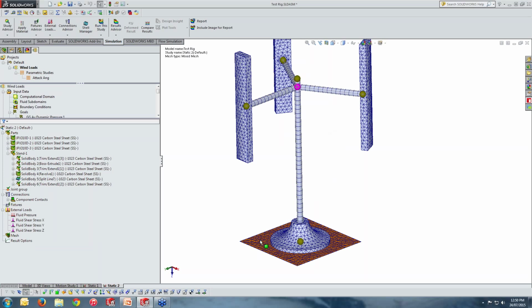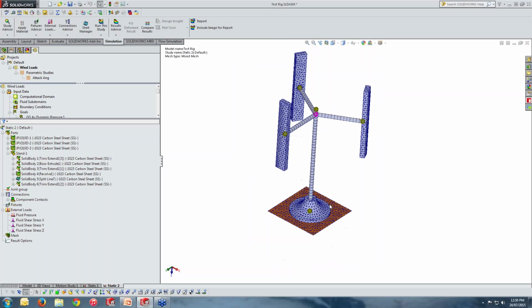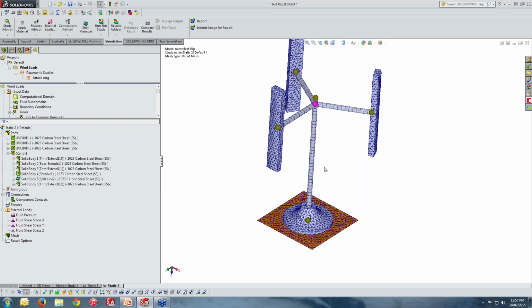Again, like from the flow side, here we again have a very important topic of having a very good mesh to converge the answer and capture all important effects. Well, that would be a very separate topic, and we are not going through this, and we are accepting everything here. But one thing for sure, our mesh should be perfect, meaning optimized, not very coarse, not very fine, and it is capturing all the important events happening in our structure.